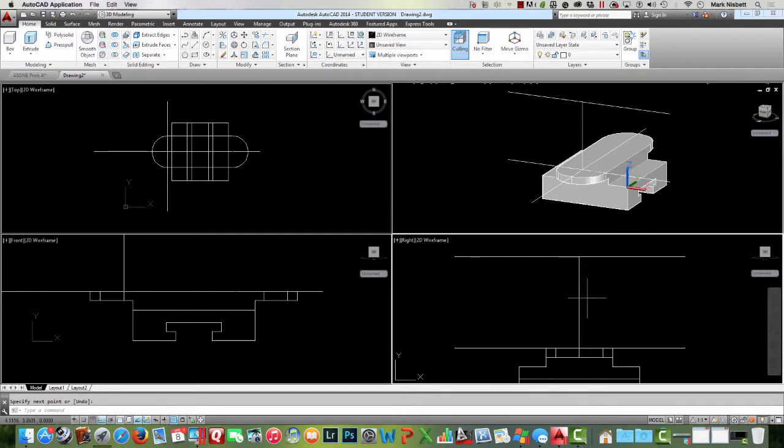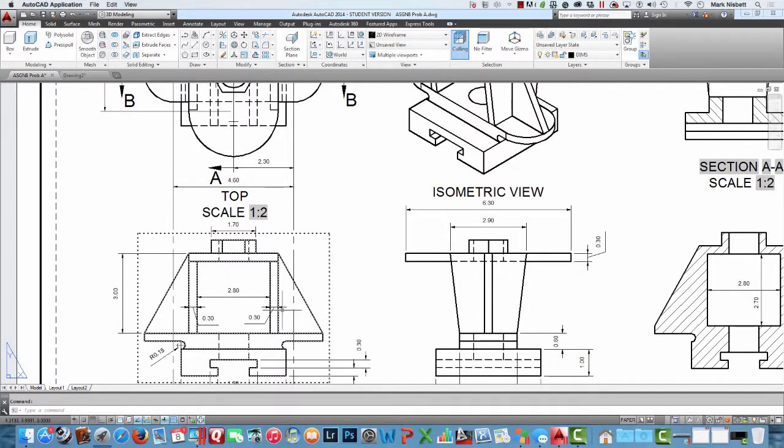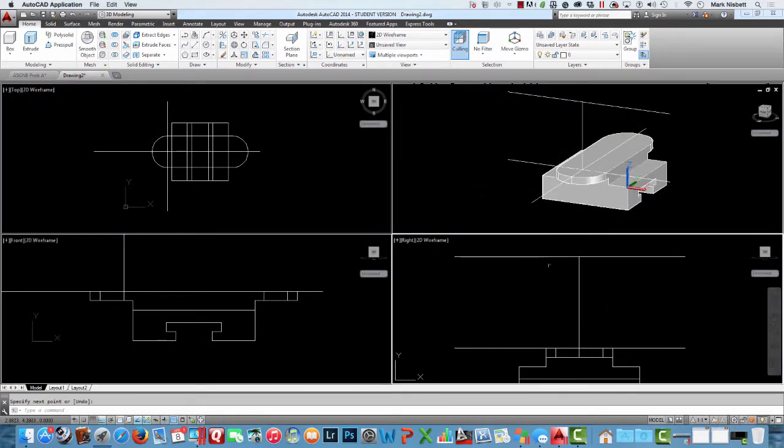And the upper portion of this here, if we're looking at this, is 2.9 in the upper portion. And then we're going to push this shape back and we're going to extrude it the depth, because we're looking at it from this side over here. We're extruding this back, and it's going to be 2.8 plus 0.3 and 0.3, so it would be 3.4. So that's what we're going to do, is create this shape.